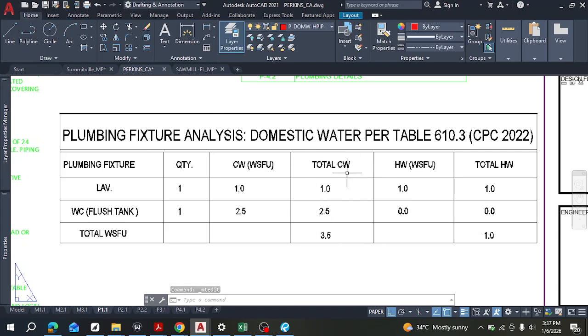So now you get your total cold water fixture units. Then you get your total for hot water. So if you notice now, there's no total for WC. So you continue and then the total is this. Now you use this in your sizing, right? Now if you remember, we saw that for 100 feet, and then okay, let's just look for that table basically.